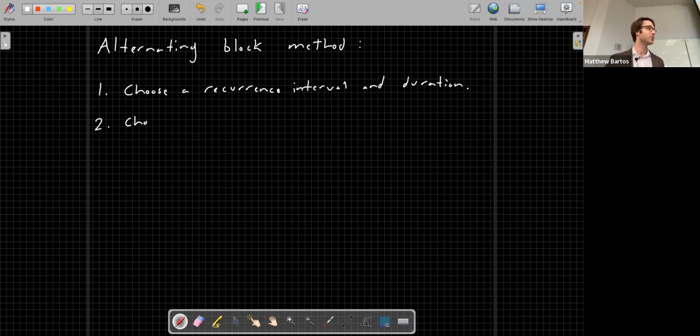Second, we're going to choose a time interval for binning. We're going to take our long storm event and bin it up into discrete increments. For instance, we might have a total duration of 3 hours and discretize that rain event into 10-minute increments.